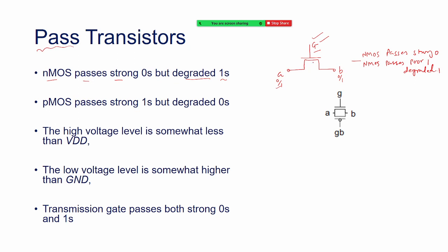And when we implement this network through the power supply units, we have a VDD and we have a ground. These two are called power rails. Essentially they are the strongest signal sources, right? When we apply input to a circuit, the digital circuit switches between 0 and 1. That means these power levels, VDD is nothing but high logic and ground is nothing but low logic. So this power level logic is thrown to the output. In other words, the output gets connected to either VDD or ground, or logic high and logic low. So they are the strongest voltage sources, either 0 volt or 5 volt, or just say high and low.